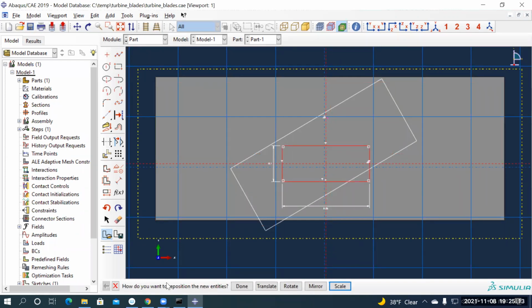So it will become a small rectangle. Before you say done, rotate. Again, the center point for rotation is 0, 0. Enter. Angle of rotation, this time let's rotate 45 degrees. Previously we rotated 30. In the same direction, I'm entering a positive value. So previously the rectangle was 30, here it's 45. And say done. And done again.